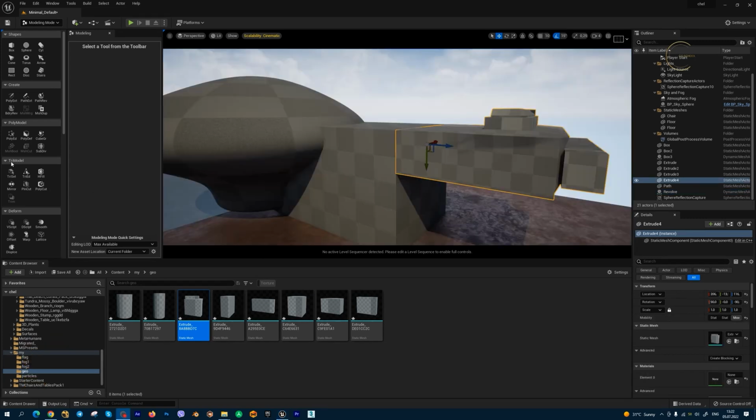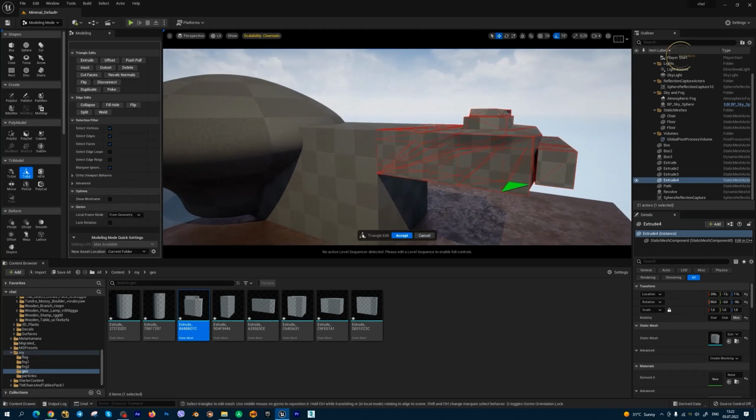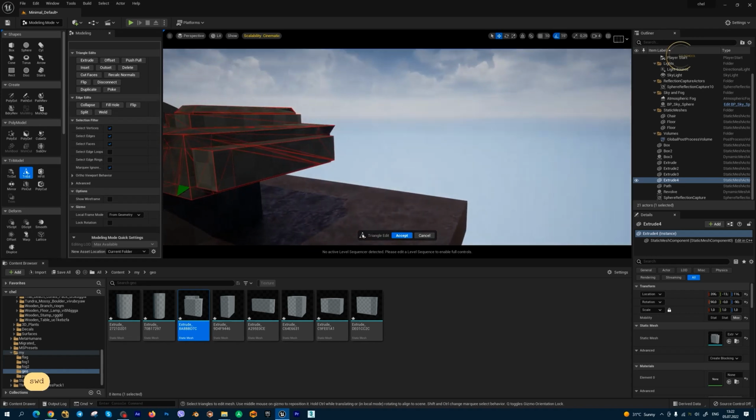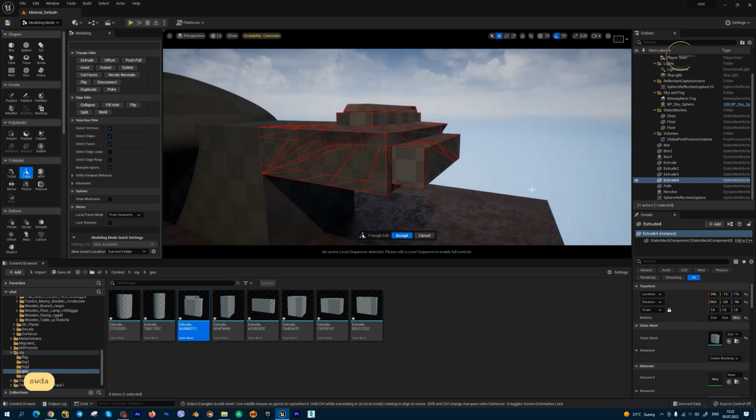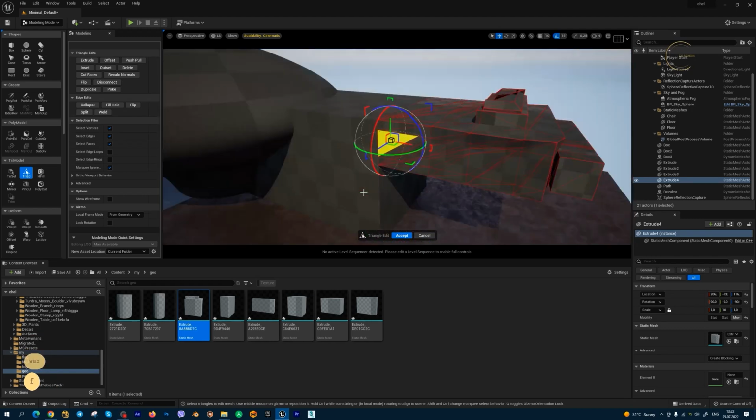The next powerful tool inside the model tools is tri add. This is the triangles editing mode. So all geometry inside Unreal Engine 5 consists of triangles, and we can edit these triangles. We can hold Shift and select a few triangles and edit all groups.